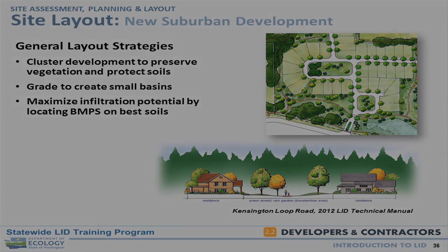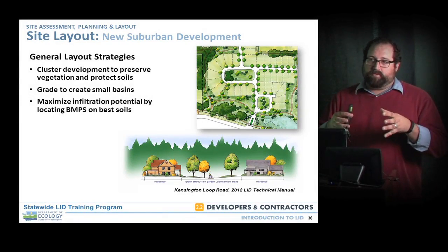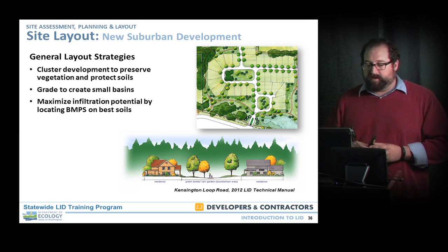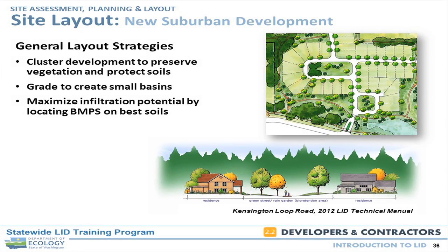Even on a high-density site, you can work with the site features to maximize some of the existing conditions and minimize some of the impacts. But clustering development, a lot of times it's done to protect trees. One of the things that's very interesting is to use it to focus development where you have soils that are maybe not good for infiltration or bioretention, and to leave your open space where you can actually effectively manage stormwater. So again, knowing the soils and the vegetation gives you an adequate picture of where to locate buildings itself.